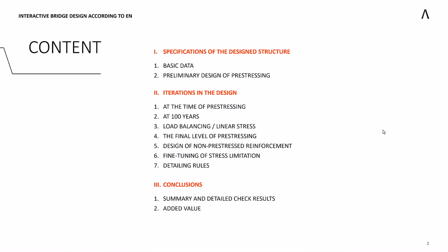Then, we refine the pre-stressing force in several steps. We perform the design of non-pre-stressed reinforcement, and then we advise on how to fine-tune the assessment of the stress limitation. Finally, we will show detailed check results, the design report, and last but not least, we will highlight the added value of Allplan Bridge design.